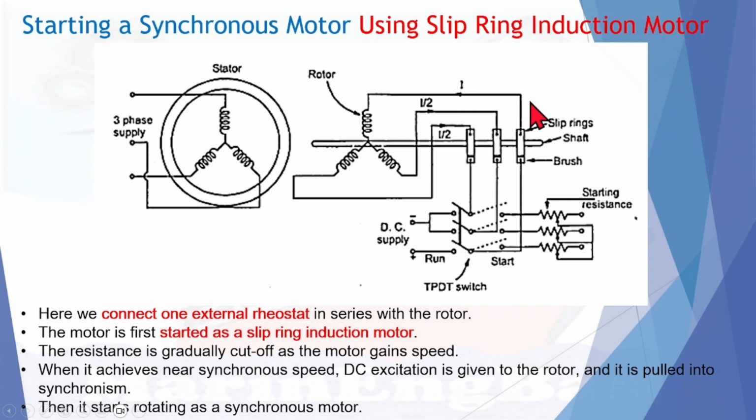The reason to use a wound rotor is normally to increase the starting torque, because the starting torque of an induction motor depends on the rotor resistance. In a wound rotor, the rotor coil is connected to an external resistance bank for starting time. At starting, you set the highest resistance value and start the motor.